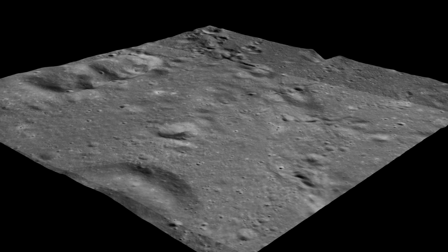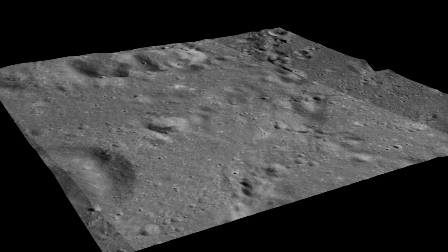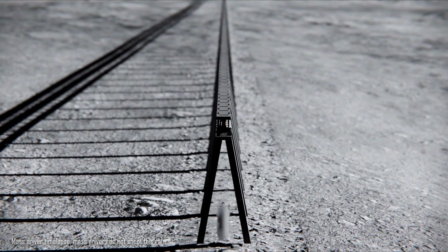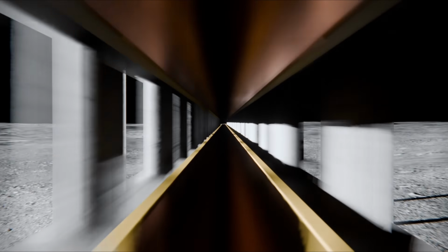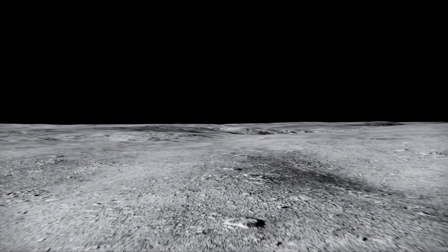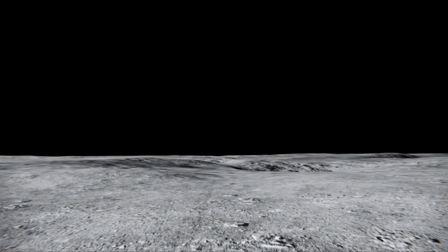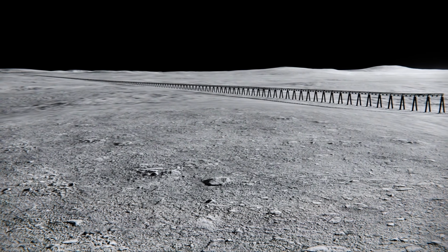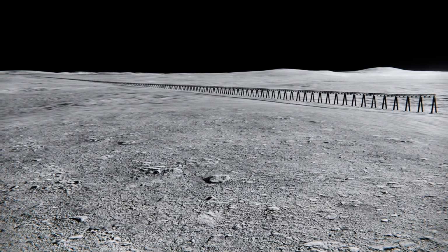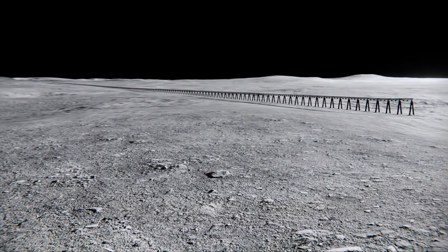So now that we have a location to put the mass driver, we need to decide the launch orientation, the azimuth and elevation at which the mass driver rocket pods leave the mass driver relative to the lunar surface. Elevation is how high we tilt the mass driver upwards, so we can do stuff like gain altitude and prevent the payload being launched from immediately flying into the side of a moon mountain. But physics mostly makes the decision for us. Tiny angles become huge over kilometer scales. A 15-kilometer mass driver elevated by just 1 degree would end more than 260 meters above the lunar surface.